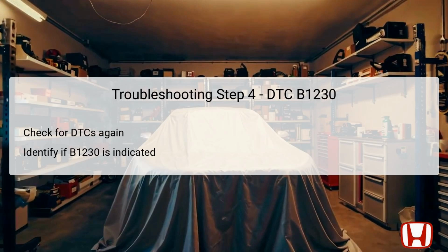After completing the self-diagnostic function, the next step is to check for any new or existing DTCs. This verification step is crucial to determine if DTC B1230 still persists, or if the system has cleared itself of errors.